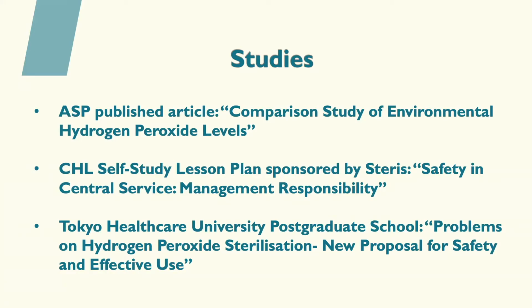So we're not talking about something leaking out or malfunctioning. It was a legitimate cycle that finished. Somebody opened the door, and these fugitive hydrogen peroxide emissions came out. So for whatever reason, during the process, the hydrogen peroxide did not fully break down or was not fully vacuumed out. And now the person opens the door and it's right up in their face or possibly on their skin.